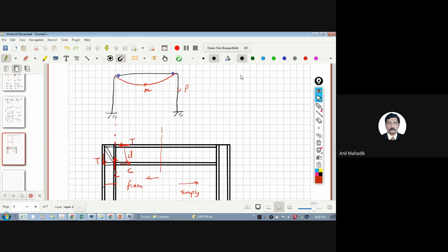Second point, the tension transfers through the flange, right? Tension develops in the flange, and it will transfer into the column through the flange in this line. So in this case, I will not provide the flange in this zone, because I know that if I connect it to the column, then it will transfer the moment and tension. So I will cut the flange over here. I'm cutting this. I will also cut the flange at the compression side.